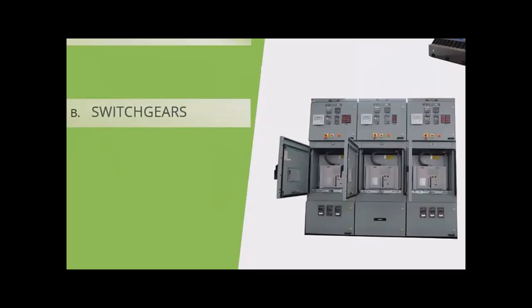Okay, the switchyards are basically means of switching your power to the next section of your power system. So now what is generated at the generation from the generator will be sent to your switchyard. Then from your switchyard, it could now be sent to your transformers, your step-up transformers. After your step-up transformer in the switchyard, we also have other switchyards. Okay, so the functions of the switchyards are numerous, as we will see later. They do the switching for us. Okay, they also help us to monitor the circuit. They do the protection of the circuit for us also, and they also help us to control whatever is happening within the circuit if it is so configured. So you see that the work of the switchyard is enormous in our power plant.